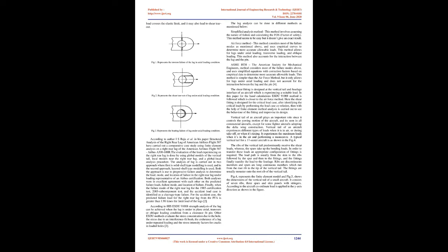2. Shear tear out. 3. Bearing failure. Fig. 1 represents the lug failure mode under the action of axial tensile force represented by the arrow, and the failure occurs across the net section of the lug in the middle region of the lug, as highlighted below. Fig. 2 represents the failure of the lug by shear tear out when being loaded axially.